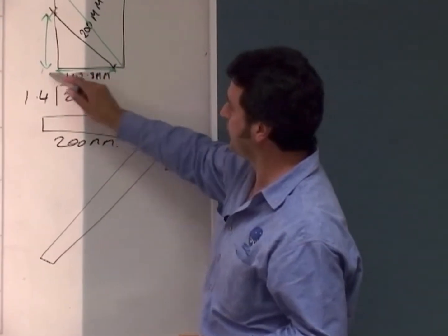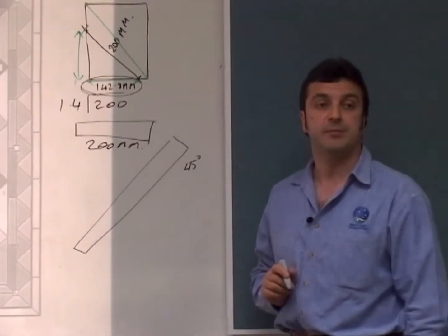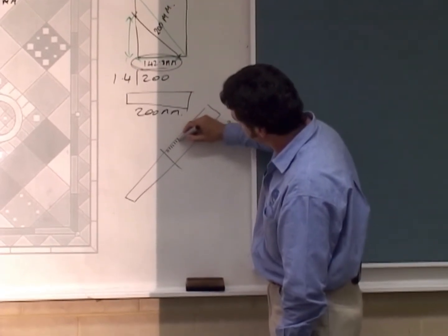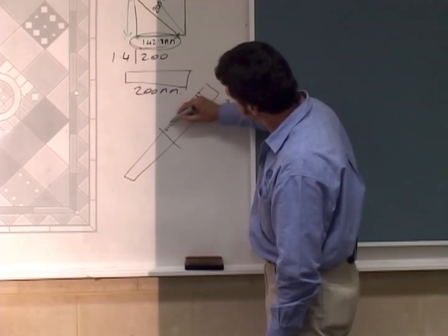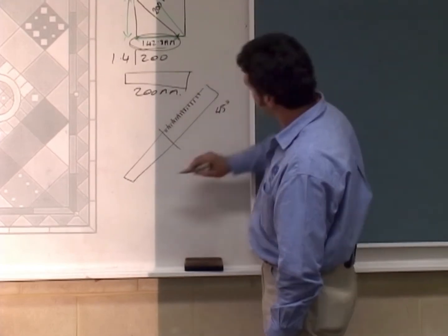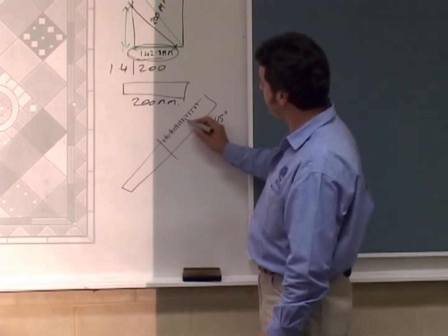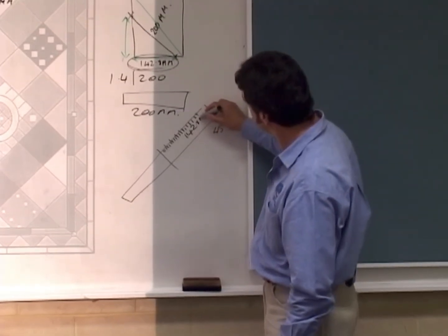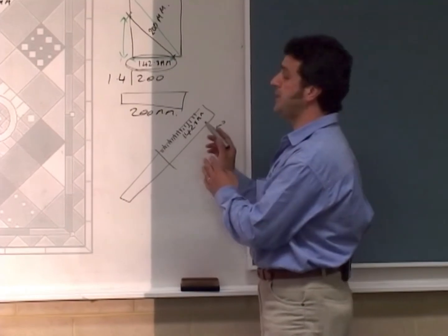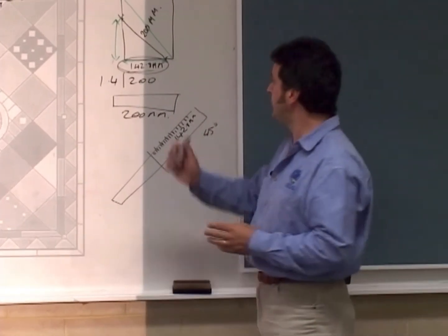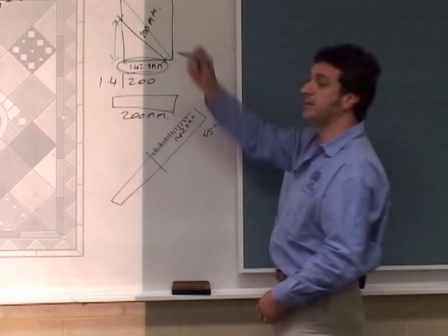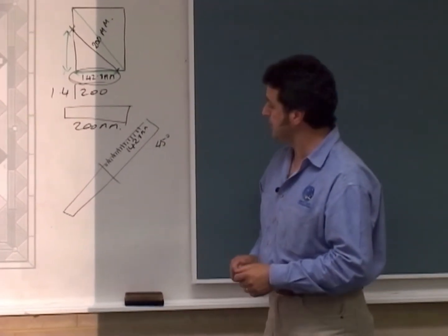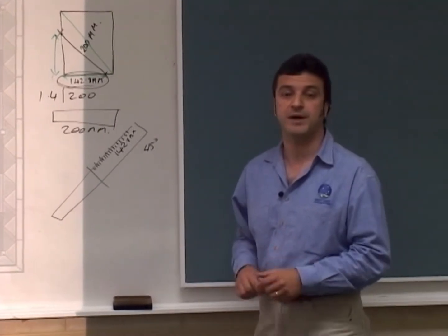Having worked that calculation out, on the tile cutter, which has all the millimetres indicated, and then the centimetres, they can run the tile down to 142 millimetres, 0.8, and that'll give them the required angle, and at the same time the measurement that's required. So it's a one-step process, which makes it really easy these days with the swivel bar tile cutters.